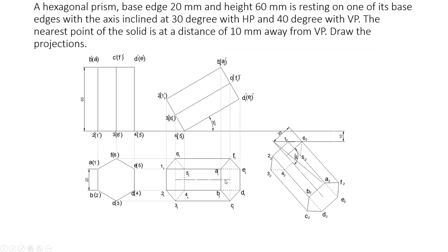you mark here, and the other distance towards downwards like this, and from here to here and here to here. Distance you mark here, and also half of this distance from here to here. So you'll get some 6 points. Connect those points, you'll get a hexagon like this, here and here. That means you are copying this diagram at 48 degrees, tilting at 48 degrees like this. Name those points with suffix 2, that is 1 2, 2 2, 3 2 etc., and A2, B2, C2, D2 etc.